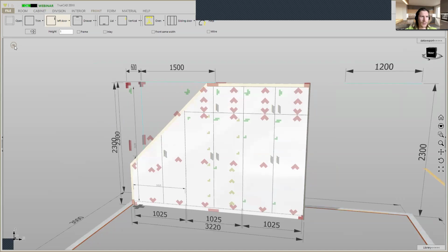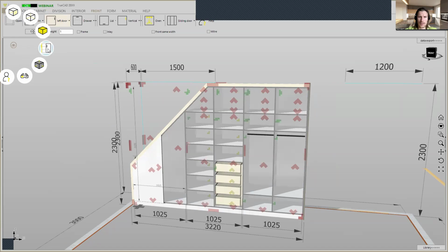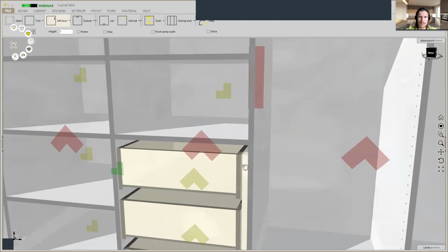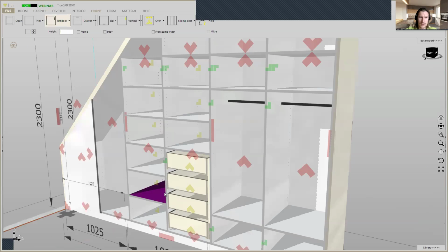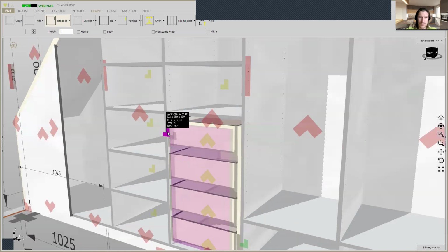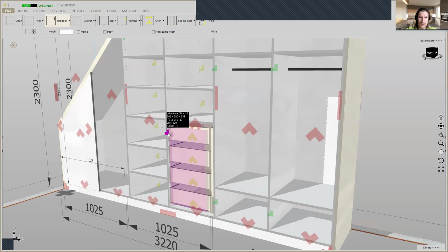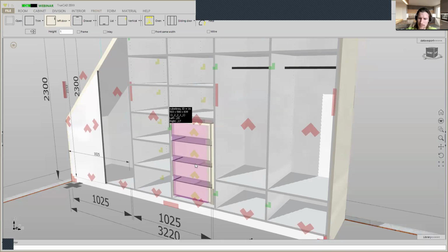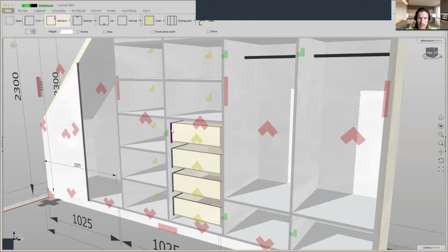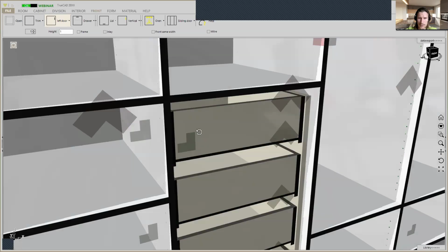One more thing, if we click here and draw the fronts invisible, you see here we have a distance panel. And if you want to have an offset in here, you can click on the smart click for the bottom area and choose offset interior, like 40 millimeter, and confirm it with enter. Then you get an offset.